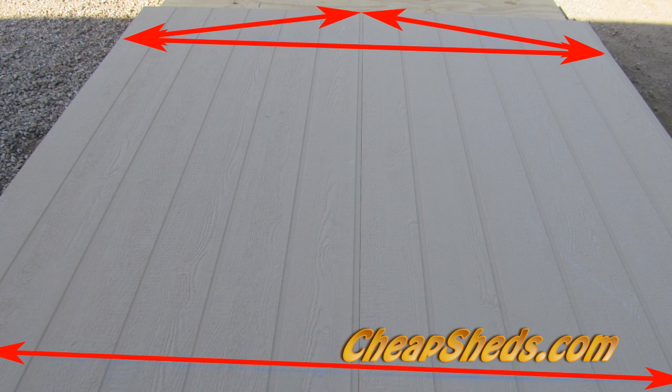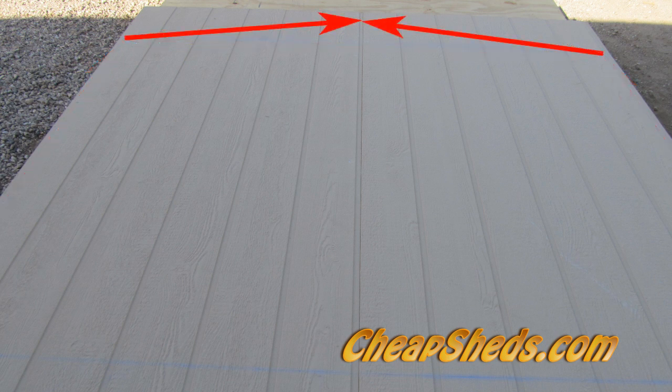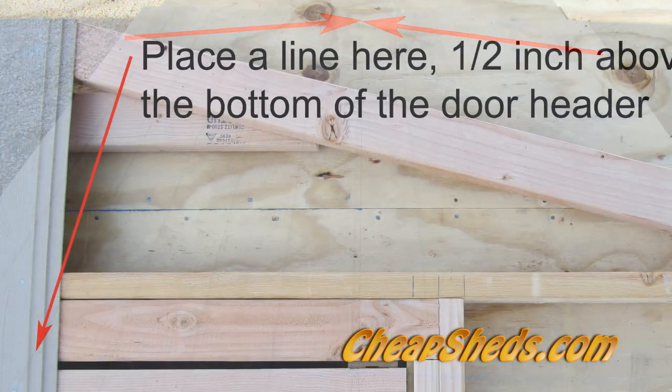Snap a chalk line along the center of the top and bottom plates and along the top of the truss where you will trim it. These are nail lines. Nail across the top plate only. Do not nail the bottom plate at this time. And nail the outside studs and along the truss inside the chalk line.